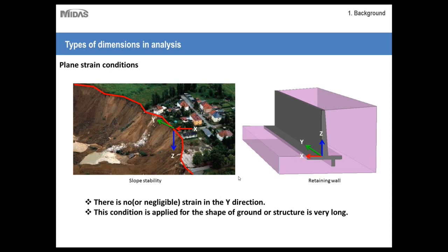This is dependent on the fact that strains in the y direction, the longitudinal direction, are negligible. So it's really up to you, the engineer, to decide whether or not 2D analysis would be beneficial in this type of project. It really depends on your project, what your clients want, the scope, the budget, etc. But just keep in mind that even though the geometry isn't perfectly symmetric, 2D analysis may be an option, as long as certain factors are fulfilled.